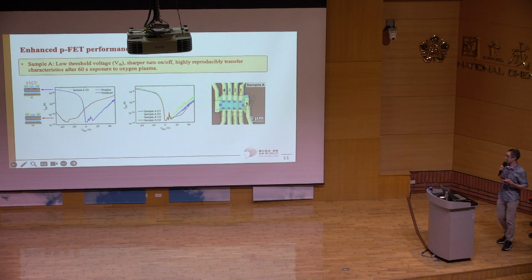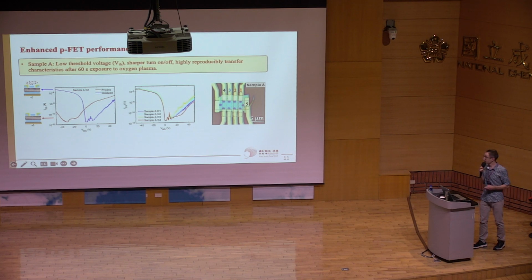One crucial question is how repeatable this process is. If we compare similar geometry contacts on the same device, we see remarkably similar transfer characteristics. The pinch-off voltages are basically exactly the same voltage, and we see very similar on currents. So that's very pleasing.